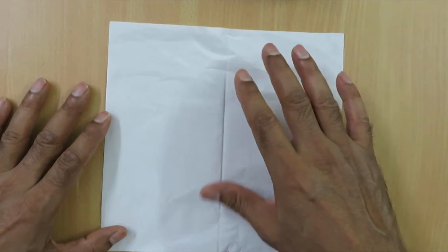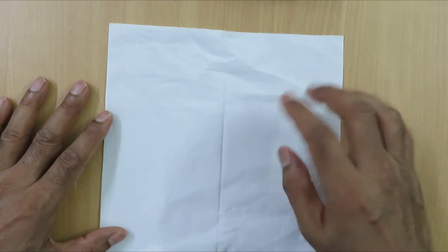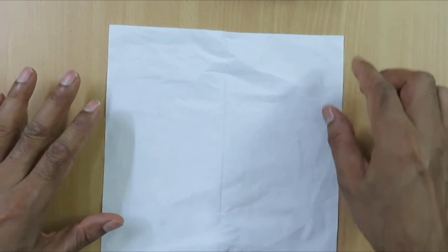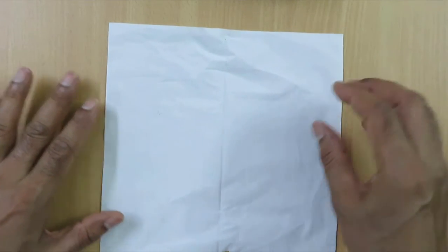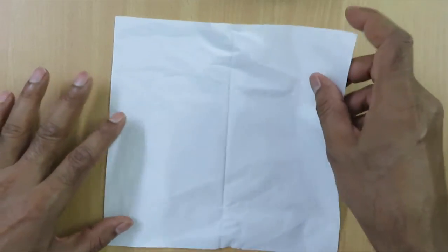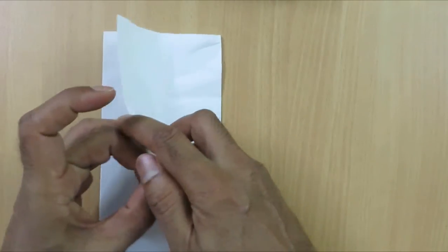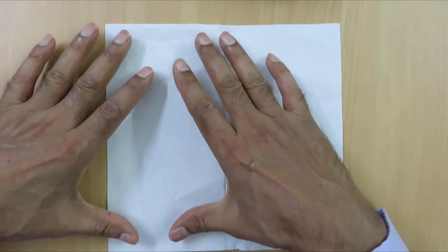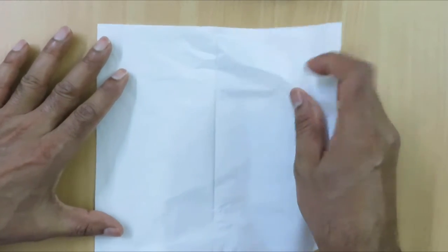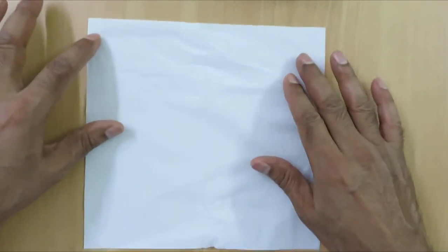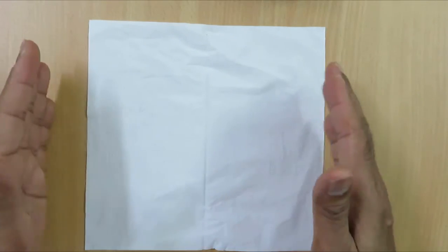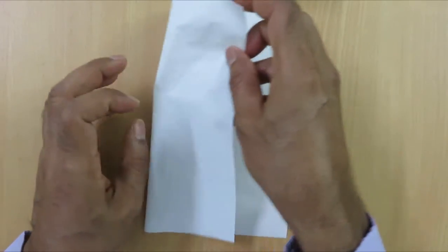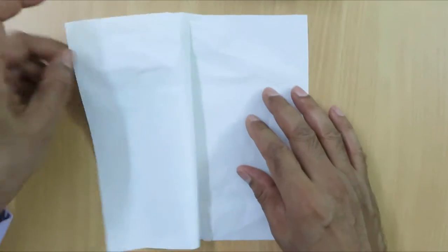That means the property of this facial tissue will not be the same in this direction and this direction. I have identified that the direction of rolling is this way because this has been stacked like this. Also, sometimes you can see some impressions along this one, which indicates that they were kept under some pressure in the roll and passed through like this. Another indication is that during the final stage, the tissue is folded like this in an automatic machine.